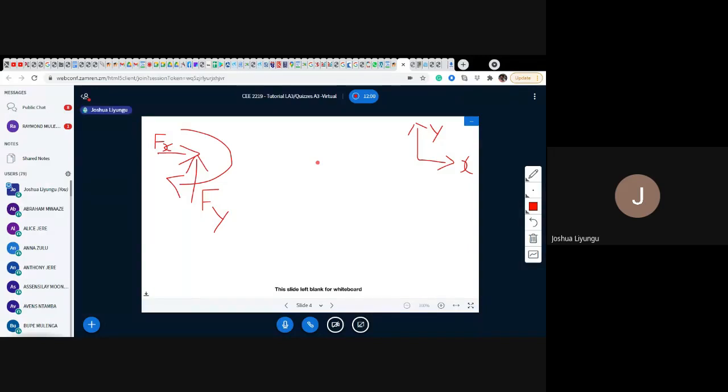We also mentioned a fixed support. A fixed support is more like a pin connection without the member itself rotating. You model it having the force in the X, the force in the Y, and the moment. This moment is preventing the member from rotating. We mentioned equilibrium in 2D and in 3D.